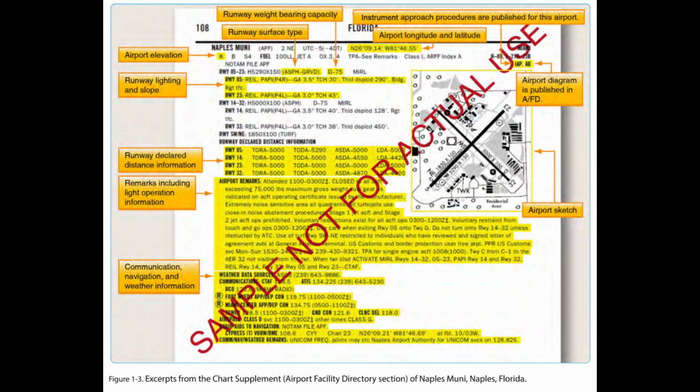Figure 1.3. Sketches of airports also are being added to aid VFR pilots in surface movement activities. In support of the FAA Runway Incursion program, full-page airport diagrams and hotspot locations are included in the A/FD section of the CS. These charts are the same as those published in the IFR TPP and are printed for airports with complex runway or taxiway layouts. Surface Movement Guidance Control System, (SMGCS). The Surface Movement Guidance Control System, (SMGCS), was developed to facilitate the safe movement of aircraft and vehicles at airports where scheduled air carriers were conducting authorized operations.